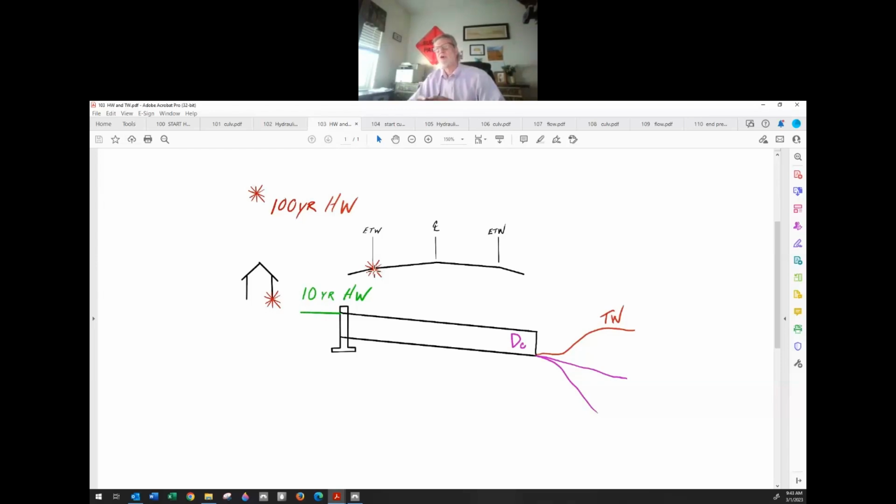So you're looking for what's called the objectionable backwater or objectionable headwater: put a plug in the culvert, let the water fill up until it becomes a problem, and that is the elevation that you're looking for. Usually you have the elevation at the flow line here, and you measure the difference in the field between this elevation and this elevation, and then just add it to it, and that becomes your headwater elevation. So you'll eventually need to go out and look into the field and take a look around.